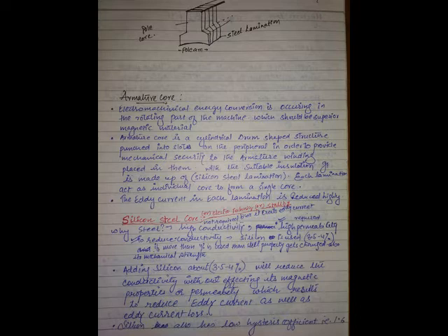Now listen. This is the commutator practically. This is the shaft. Inside there will be a shaft coming out. It is rotating continuously. Coils are inside the armature. Now you will connect two brushes to collect current. When you connect two brushes like this, which are stationary, and if you want to connect the load now, when you connect the load, automatically current flows.